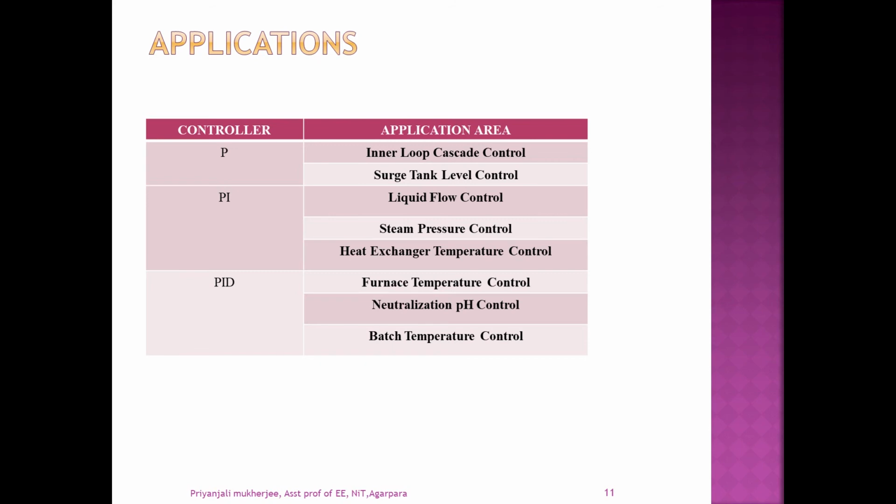Another application is the neutralization of pH control, which is widely viewed in the industry as a challenge to control because pH is highly nonlinear and its behavior changes from one operating range to another. The buffering effects of some material can curb what would otherwise be volatile dynamics until the buffer is saturated.